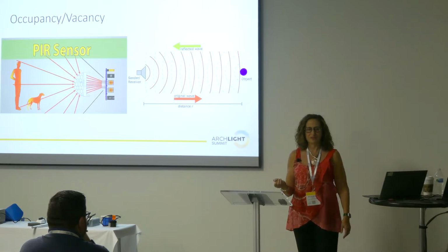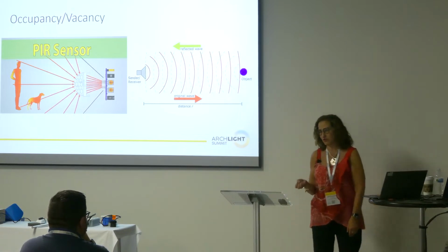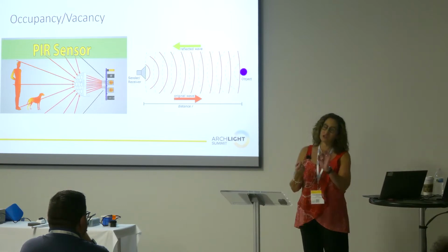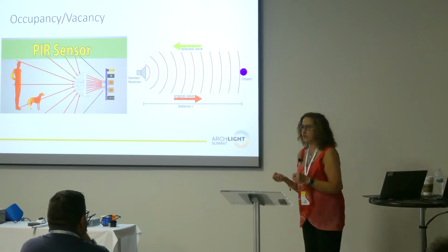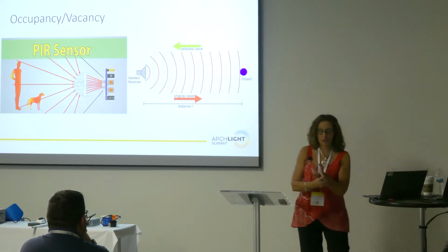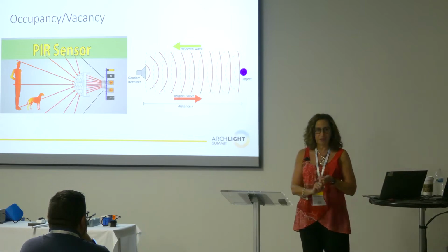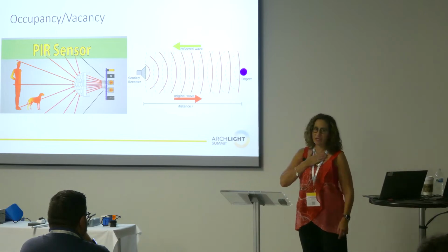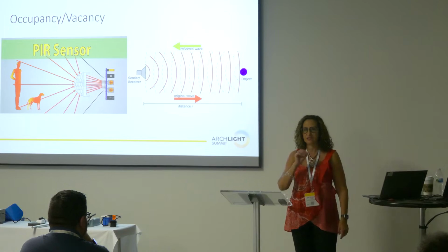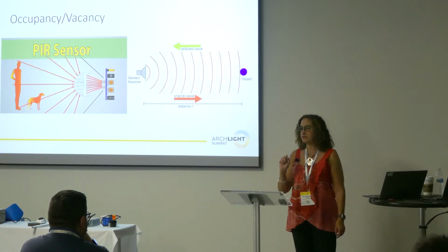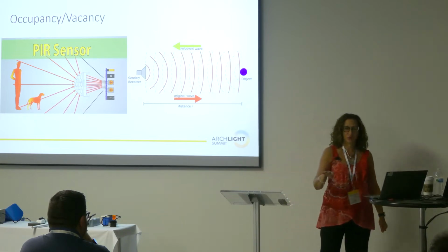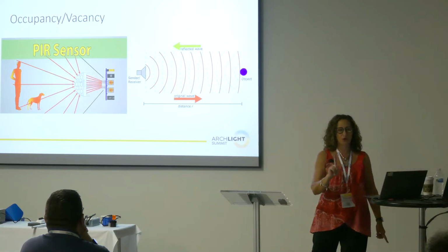Why is that a bad thing? There you go. Infrared cannot pass through the bathroom stalls. So we have two options. Option one is, and I actually use both options because I'm a belt and suspenders kind of gal, in your control intent and in your sequence of operations, have one load in the bathroom. In my case, if you happen to be in a commercial restroom that I've designed, it's the slot along the wall that never goes down to less than 30%. Ever. Room is empty, slot is on at 30%. We'll talk about why that's important in a minute. So that's option one, that's the belt.